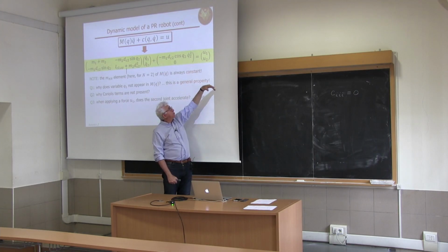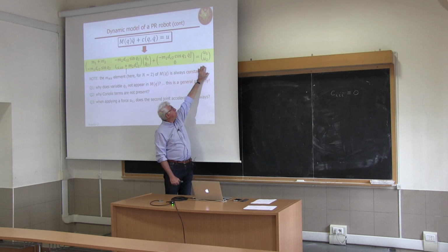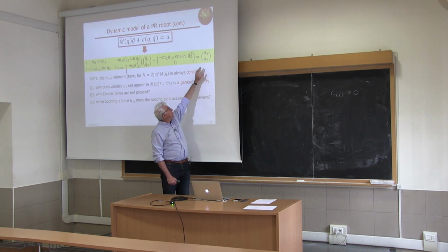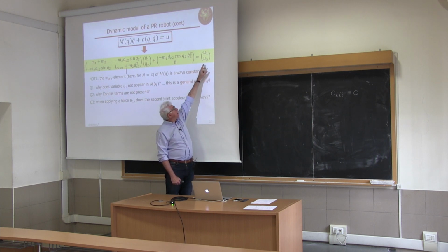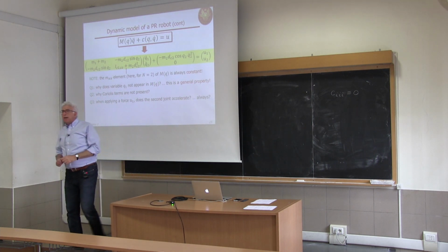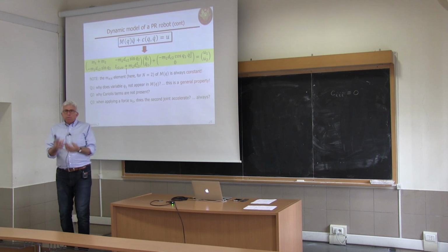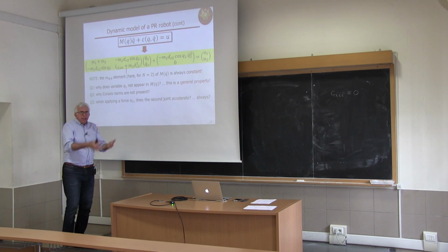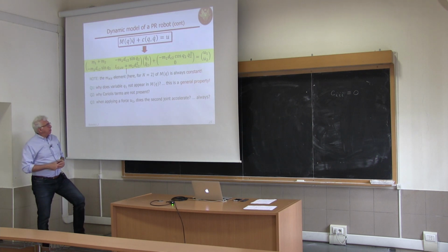If you neglect all non-conservative forces, let's say all dissipative forces and other external forces, so only the motor torques, this becomes a force on joint 1, and U2 is a torque because joint 2 is a revolute. It's the torque produced by the motor once reflected after the reduction element or transmission element that you may have. We don't go into detail as we did for the actuated pendulum, but the same applies.